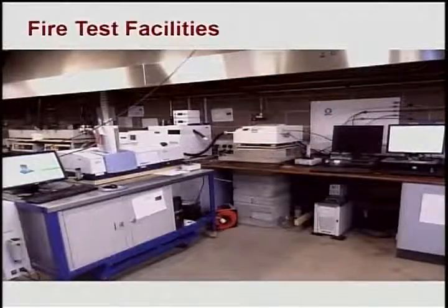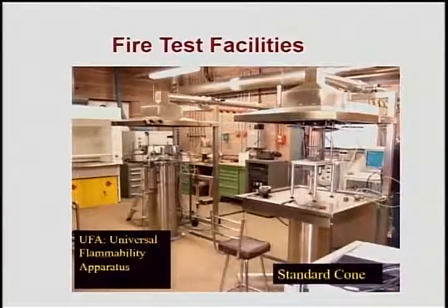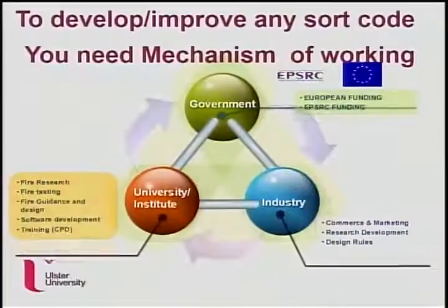On the other side, we can learn the chemistry, the TGA, FTIR, and the gases, coming from the specific characteristics of the material you test. So you have to understand the physics and chemistry before it comes to the engineering application, which is the cone calorimeter. And from the other side, this is our development, which is called the UFA, Universal Flammability Apparatus. It's unique, it's our idea, which means the sample is not open to the oxygen, but it's inside and mixed with other gases as if the element is in the rear compartment gases.